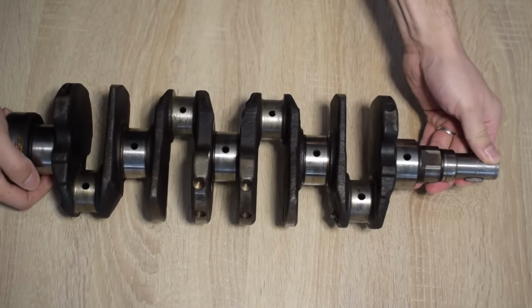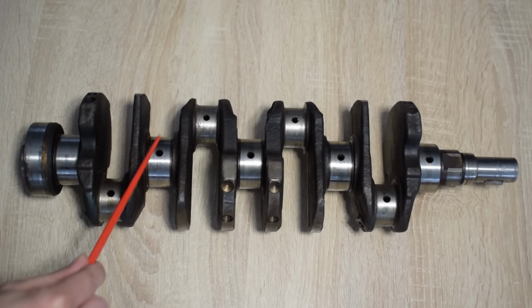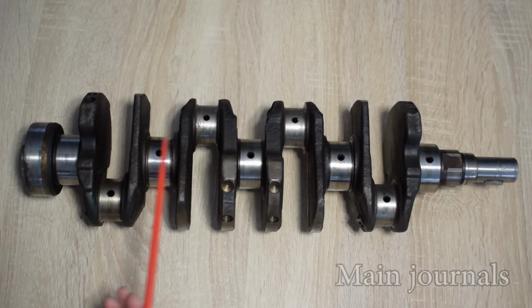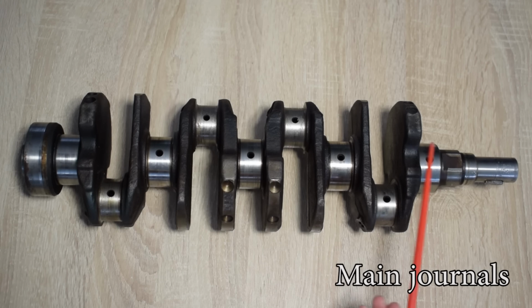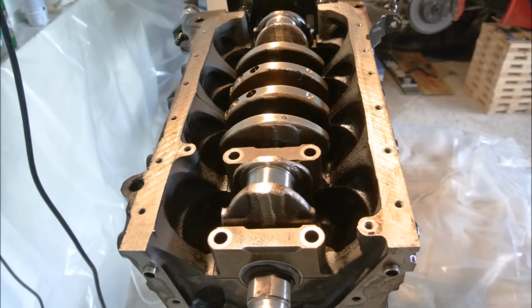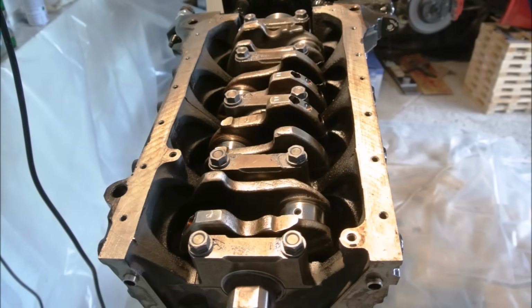Now, before we dive deeper into the world of the crankshaft, first we have to know what is what on a crankshaft. So let's get our crankshaft again and let's check it out. Now, all internal combustion engine crankshafts have main journals and rod journals. So these are the main journals. Now, the main journals is what the crankshaft itself rotates on. And the crankshaft is held in the engine block at the main journals by the main journal bearing caps.